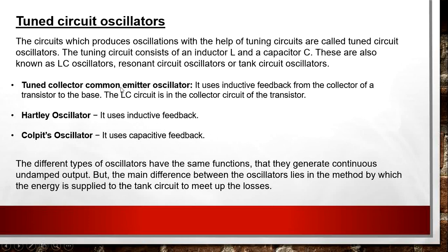I am going to discuss three important tuned oscillators one by one. First one is the tuned collector common emitter oscillator. It uses inductive feedback from the collector of a transistor to the base. The tank circuit or LC circuit is in the collector circuit of the transistor.